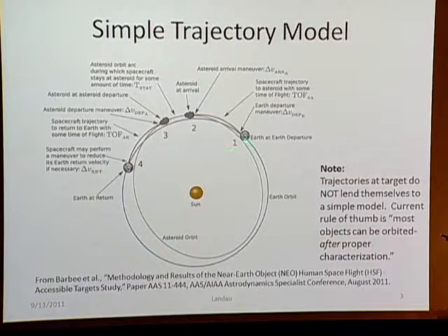And then once we know the velocity arriving at the asteroid, since the asteroid doesn't have any mass, the delta-V is just to kill off all the relative velocity. So that's just sort of, I don't know, glossing over half a semester or so of orbit dynamics. But that's basically the model that we use to generate all of these trajectories for the interplanetary stuff,